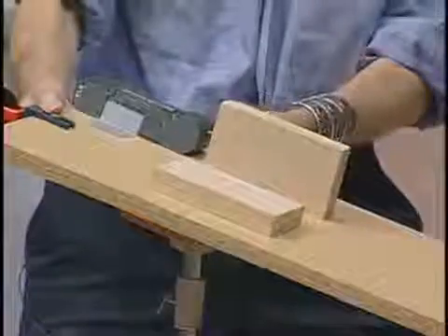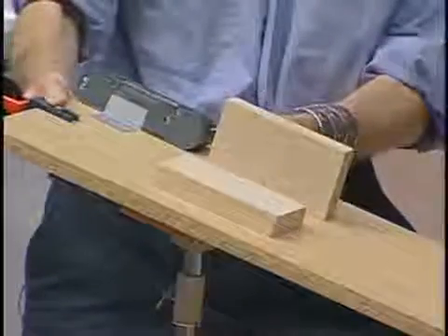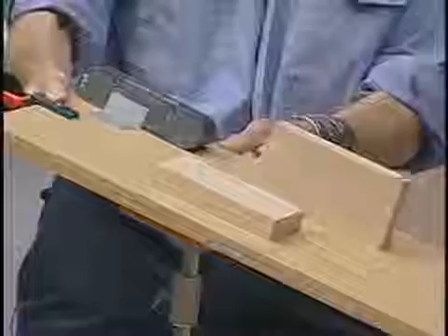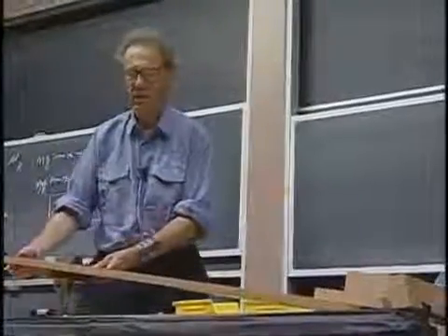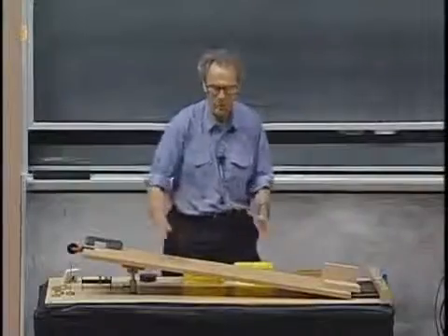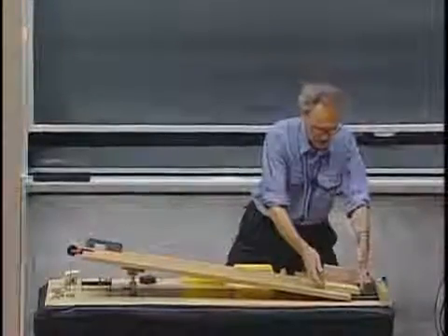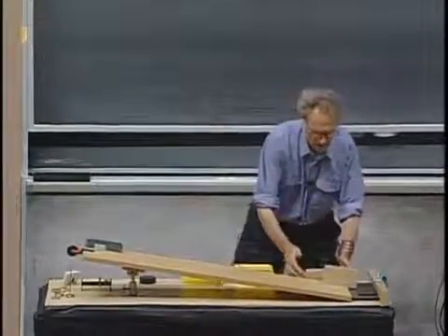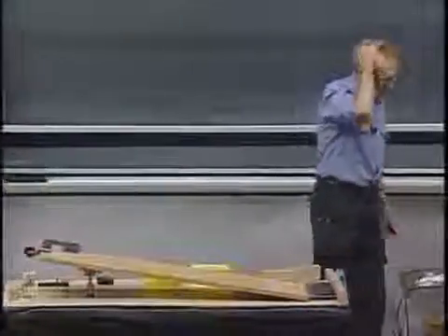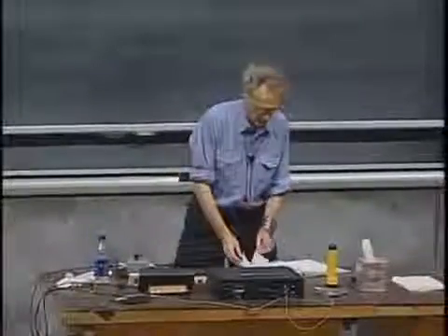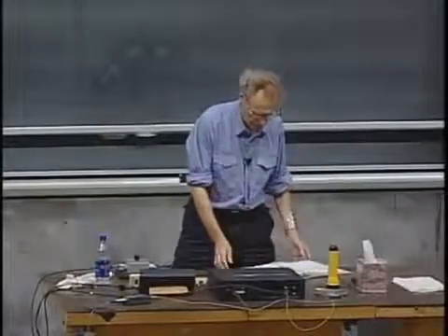14 degrees, 16, 18. One goes, and the other one follows, within 0.2 of a degree. And the reason why there's always some difference, of course, is that the plank is not exactly uniform. I have to be careful that I don't touch the critical surfaces. So you have seen difference in friction coefficients, and you have seen there's almost no effect on surface area, and there's no effect on the mass.